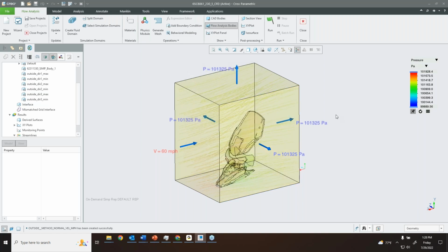Okay, so basically what we just did was we set up our input and output parameters based on the results of this simulation. Now we can use those to optimize our design or to change some things around, maybe investigate if we change this, right, what happens? If we change the velocity, what happens to the pressure, and inversely as well.